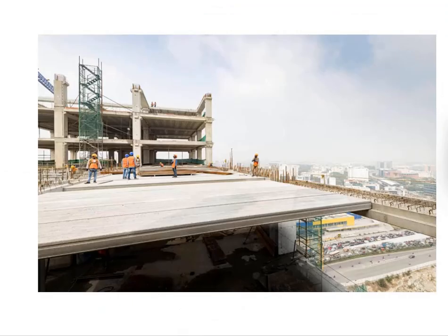You know that precast concrete structures involve prefabricating the structural elements in the factory, transporting them to the site, and then installing them one by one at the construction site. If you observe this beam here, you have the hollow core slab only on one side. This beam is subjected to torsional force, as there are no forces on the other side to counteract the vertical force due to the hollow core slab.